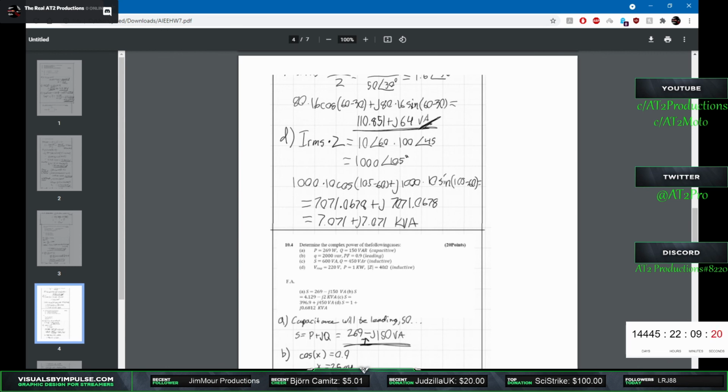So it was cooked. I don't know if shorted out is the right word for it, but because it's the air core, we lost one of the two elements and it just went straight short. It wasn't doing its job. What the dynamic braking resistors do is take that regen current being thrown back onto the DC bus, which will cause an overvoltage, and bleed that excess energy off as heat. Yes, it is inefficient as fuck when you look at it that way, but it saves your logic devices. And so what else are you going to do?